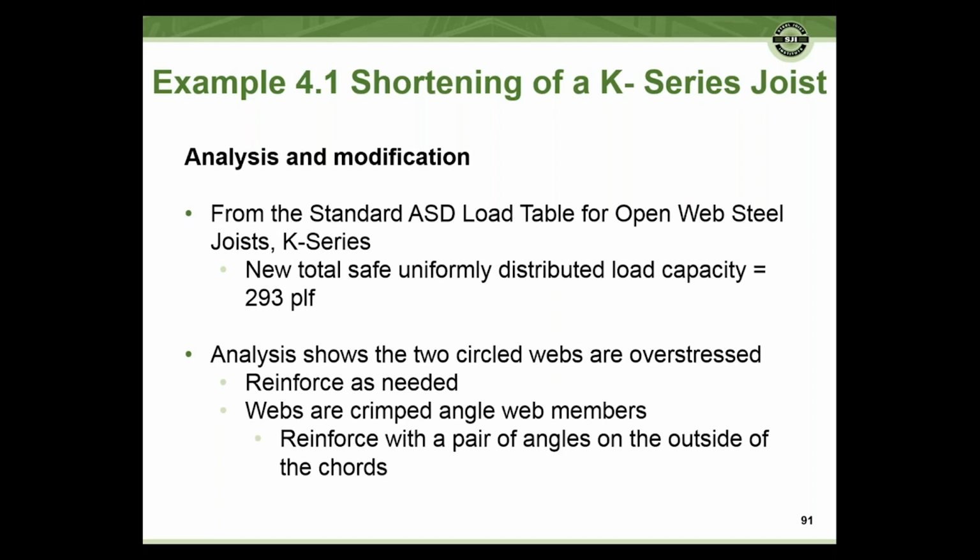Excuse me, I don't know where I got kips from. We analyzed our K-series joist for 293 PLF, and our analysis revealed that those two circled webs were overstressed, so we're going to need to reinforce them.